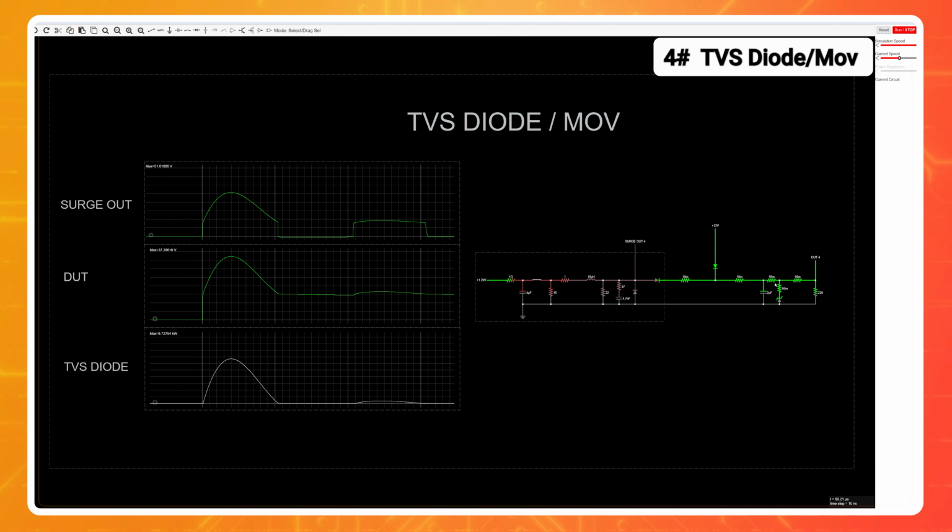So what this circuit really shows, the key thing about TVS diodes, is that unless the diode fails, it will pretty much clamp the voltage to whatever that clamping voltage is. So as long as whatever else you do to the circuit allows this TVS to not die, you're going to protect what's downstream. That's really important, and it's something I'll come back to when I show the final circuit.